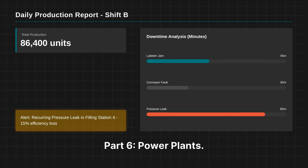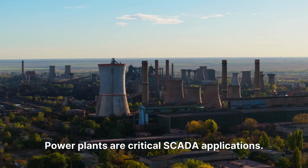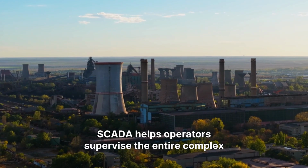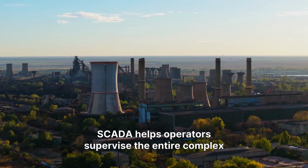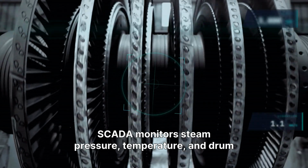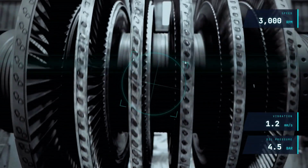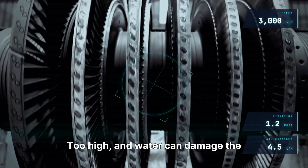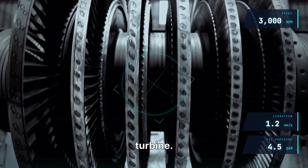Part 6. Power plants. Power plants are critical SCADA applications. Even a small mistake can cause grid disturbances. SCADA helps operators supervise the entire complex safely. Boiler monitoring is first. SCADA monitors steam pressure, temperature, and drum level. Drum level is critical. Too low and tubes overheat. Too high and water can damage the turbine.